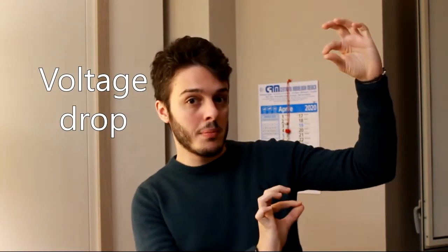Let's recap. First, in order to talk about voltage, you need to choose 2 points of which you want to know the voltage across, or sometimes called the voltage drop across the 2 points. Step 2, you choose a positive direction for the voltage, which corresponds to the action of choosing a reference and the point. Step 3, you deploy your solution methods and you get your answer. But careful, because it might as well be negative.